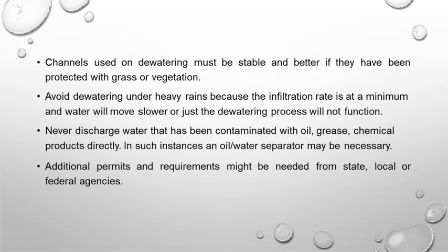Okay, so as we know, the reciprocating pump consists of a cylinder, piston, suction valve, delivery valve, suction pipe and delivery pipe. The reciprocating pump is one of the positive displacement pumps because in it liquid is pushed out through the cylinder by actual displacement of the piston.